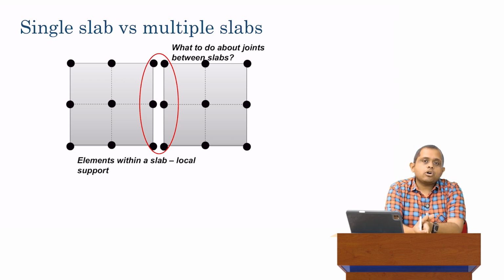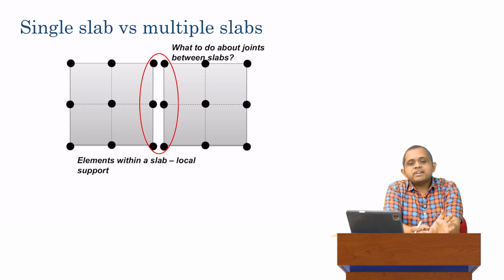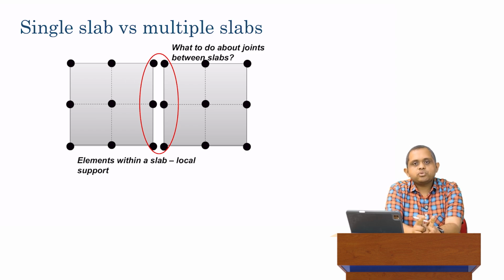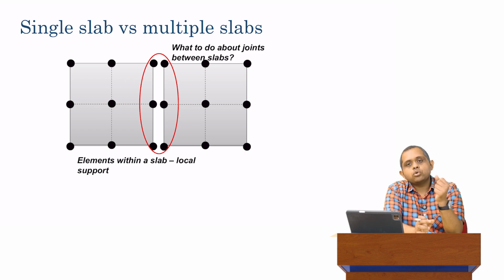If you recall, and this is actually a pretty big jump that we're making, if you recall Westergaard's theory as well as subsequent modifications, we studied that in module 2, we only discussed one slab. Even when we had joints, we discussed the failure of the dowels at the joints, but we never discussed how the presence of multiple slabs and some connection between them is affecting the behavior of the slab itself. We studied each slab on its own as though it had no relationship with any adjacent slabs.